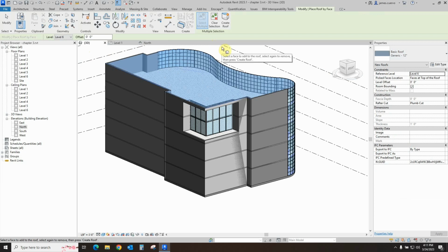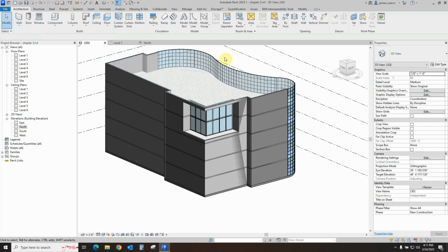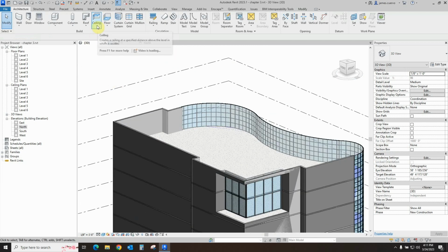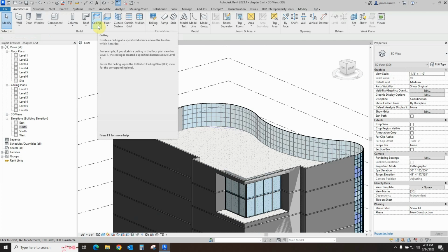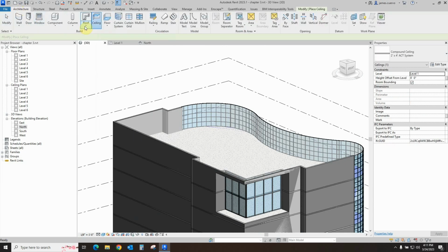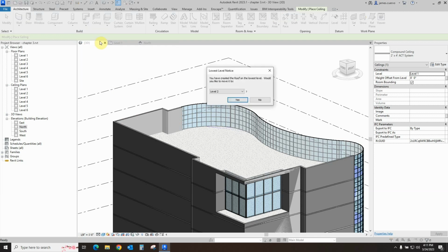So let's go ahead and see how it would really be if we wanted to create one that has an offset. That is actually done in this fashion, okay? We go to ceilings. Oops, sorry, wrong place. That's not ceilings. It's actually roofs. But instead of going roof by face, which doesn't allow us to give an offset for the overhang, I'm going to say roof by footprint.